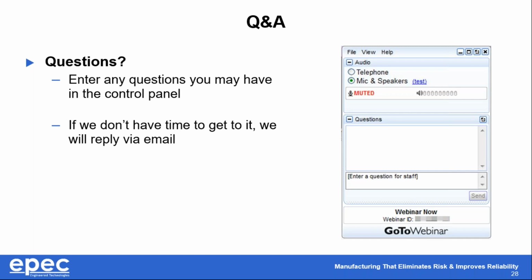What is your process for attaching the wire to PWB? I believe that's a printed wiring board. The response we'd want to give would be to attach a wire to a PWB or PCB. Really, there's two options. You either need to crimp onto something that's then attached to the board, or you're going to solder directly to the board. Some projects actually will do both.